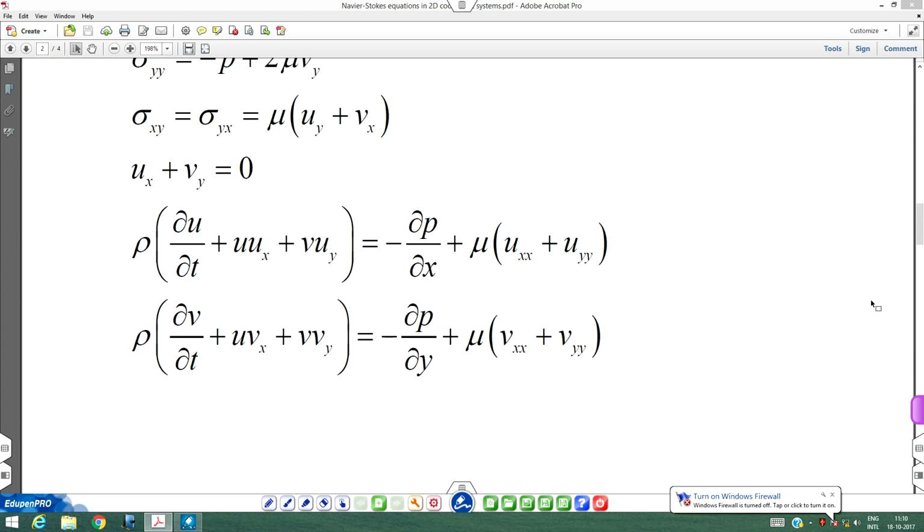You can see it is not as if you have 3 equations and the 3 are standalone. The mass balance contains u and v. Momentum also contains u and v and pressure. The other momentum also contains u, v and pressure. So, you have to solve them simultaneously. Okay, so, the 3 equations, anytime you have coupling, the complexity goes up, unless you can decouple very quickly. But here there is no obvious way in which you can decouple the governing equations.